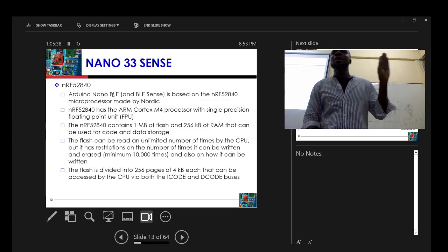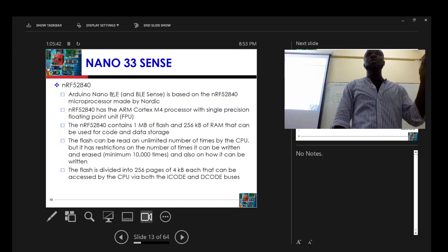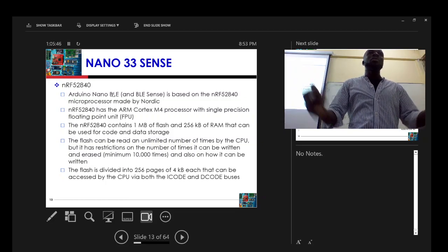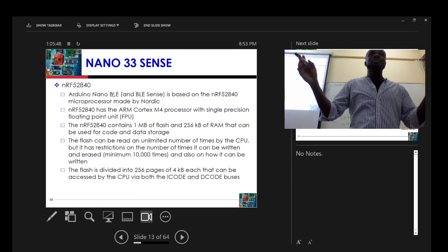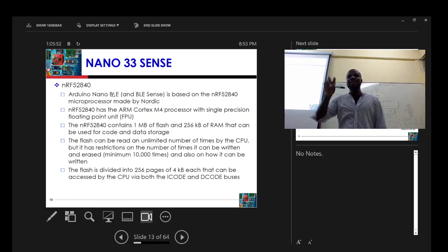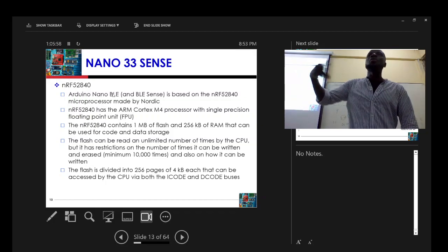Your board, the flash might not work again. So it means that you cannot upload codes on it anymore. So anytime you are uploading a code, you need to be sure that it works, so that you will just run the code once. If not, once you are uploading the code all the time, you must know that the life cycle of the flash is also going down. Right? So don't go and buy a board and just upload codes.